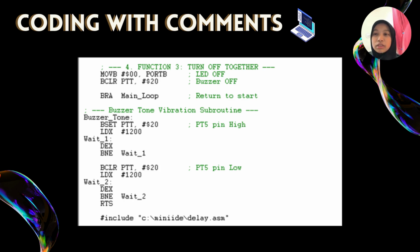We are sending a signal to port T, BCLR, which is 02, to turn off the LED and buzzer. This happens after someone no longer presses the push button. Below that, you can see there's a BRA that goes back to the main loop assembly language again, so the function will work again like how it used to.